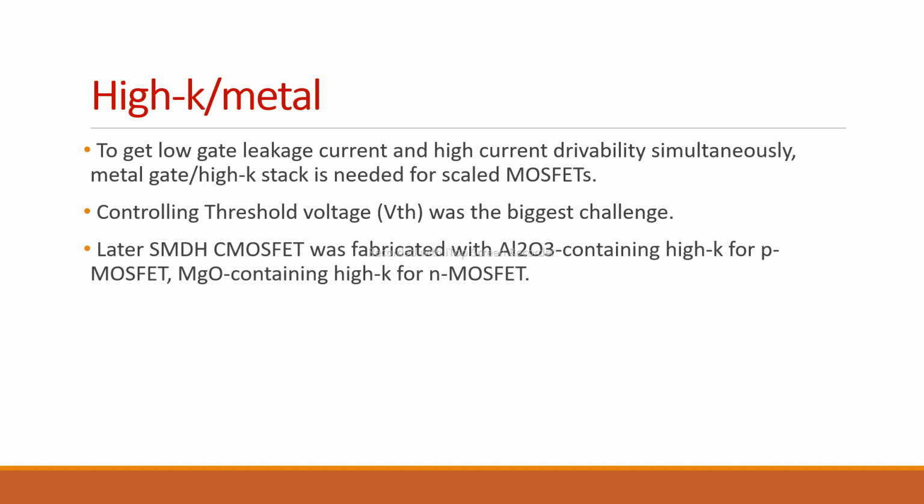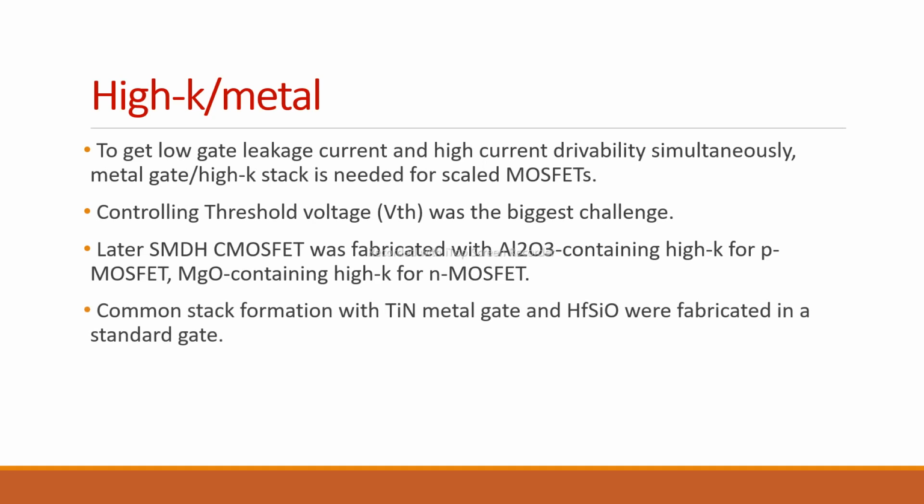Before this technique, dual metal gates were proposed, but they still suffered from insufficient threshold voltage control. So here the single metal and dual high K gate stack is proposed in this technique. In this technique, SMDH CMOSFET was fabricated with Al2O3 containing high K for P MOSFET and MgO containing high K for N MOSFET.